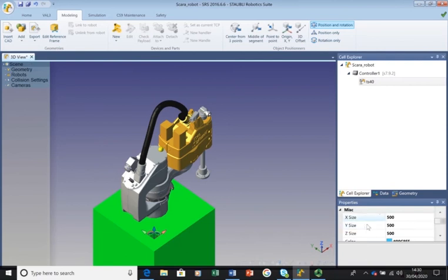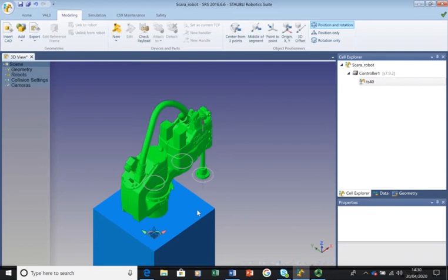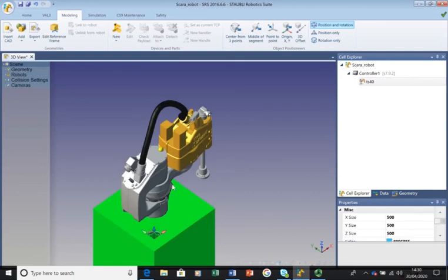Sometimes the properties window appears, but nothing's in it. It might be because you've accidentally clicked somewhere else, and the object's not selected. So it's offering properties, but this blue box is not selected. So if you click on it, let's click on it again. If it struggles selecting, you can always select it in this tree menu down the left hand side. So I've got a box.